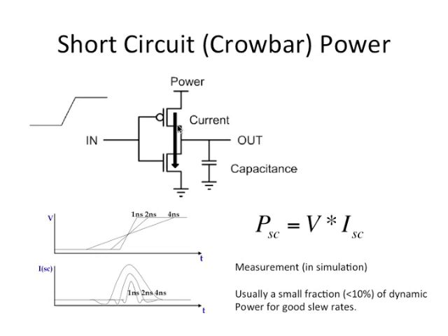No, this is just to see what it is that we are trying to understand out here. We are trying to understand what happens to the shape of this short circuit current and the peak value of the short circuit current, right? No, but we just saw that you could have no short circuit current when you have an ideal step, for example, not an ideal ramp.